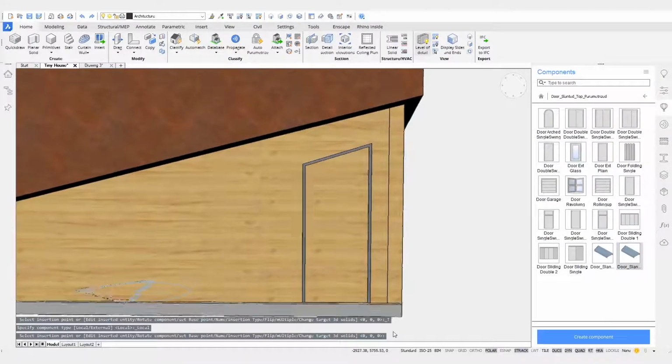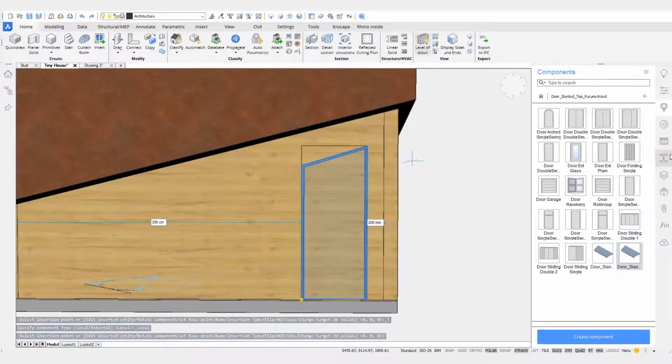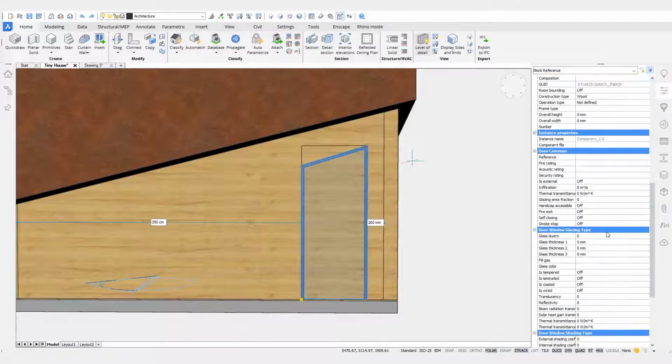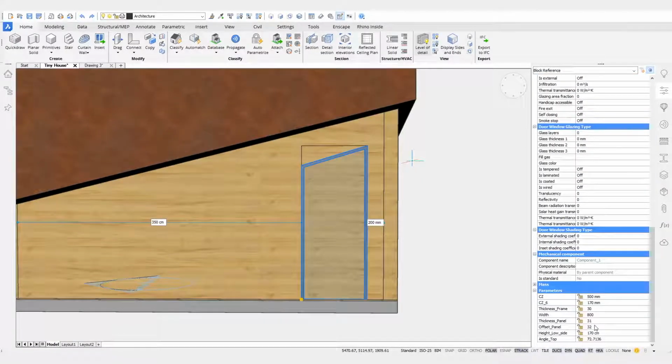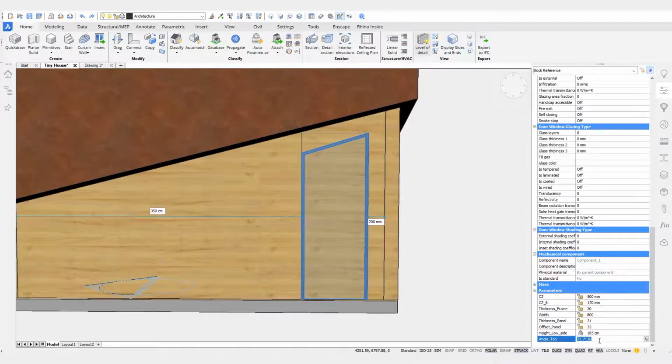And now I should be able to find these parameters in its properties. And here I have them, and I can now, in this case, change my top angle to, for instance, I think it's about 75 degrees, so it fits better. Change my height a bit, things like this. So that's how hard it is to create fully parametric objects for your library.